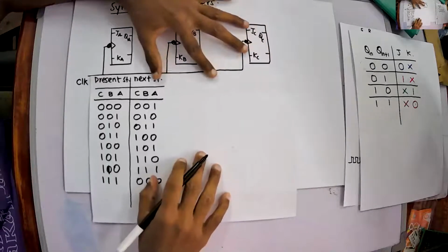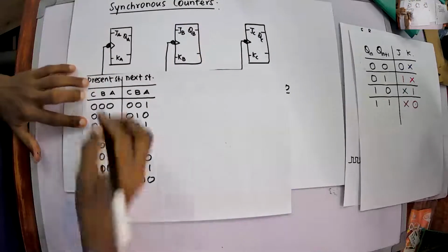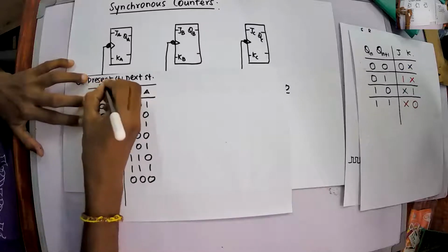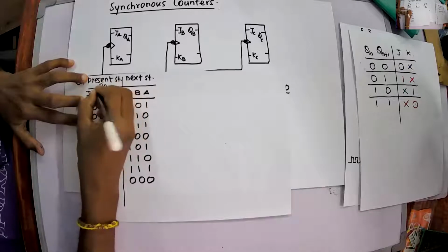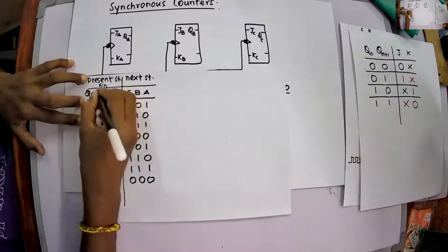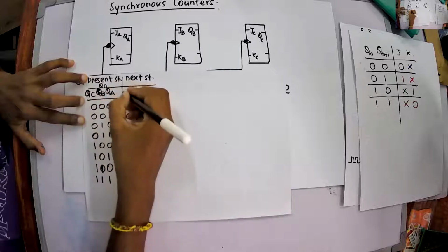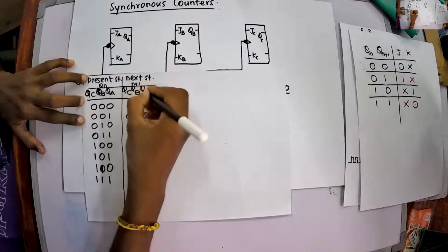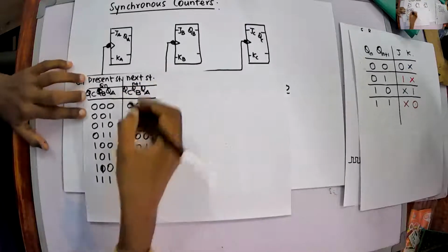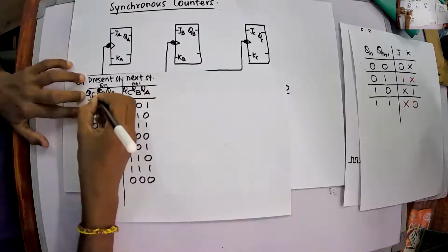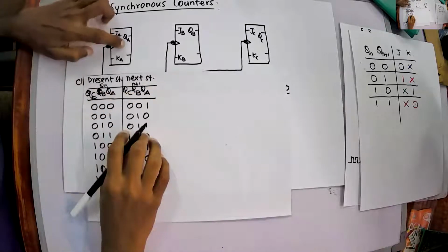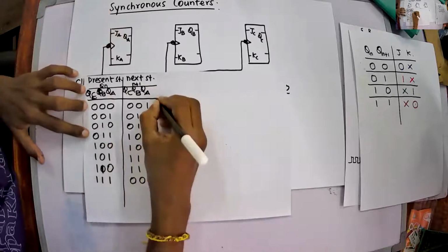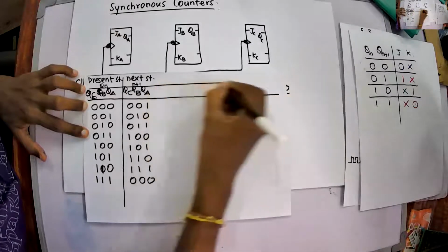So now we have filled a state table, right? So I can make it as, these are my Qn of JC, right? This is QC, QB and QA. This is n plus 1 of QC, QB and QA. Or else I could say that this is Qn of C, right? The present state of this flip-flop, right? So now I can write the excitation table in the reverse order,